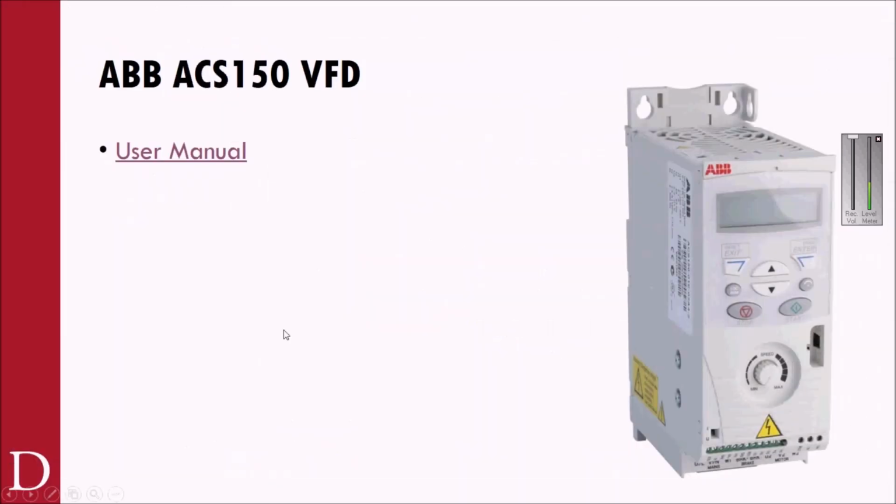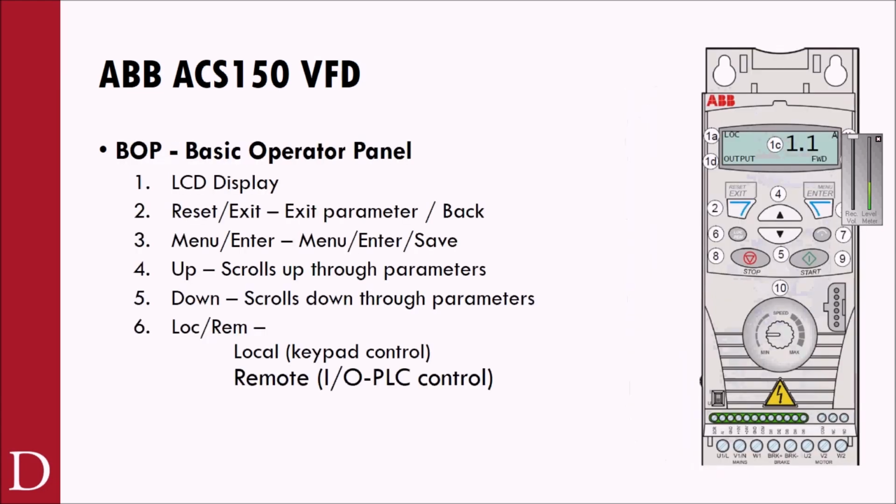So what I will tell you is anytime you're going to work with a drive, it's going to be important to dig into that manual, especially if it's the first time you've used a particular drive or any type of control, PLC, motor drive, HMI. You want to become intimately familiar. I'd even recommend reviewing that manual for an hour or a couple hours upon receiving it before I even went ahead and installed it. It can eliminate a lot of problems later on.